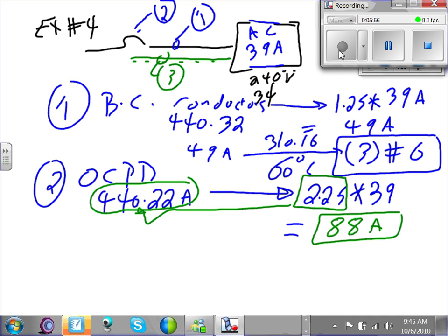What does it say, go up? For motors, it says go up. This one, if you read the article, 440.22, says shall not exceed. There's no exception to go up. If it says shall not exceed, can you go up? No. So if you can't go up, and you don't want to go to the bar and cry, and you don't want to custom design a fuse, what's your only option? To go down.